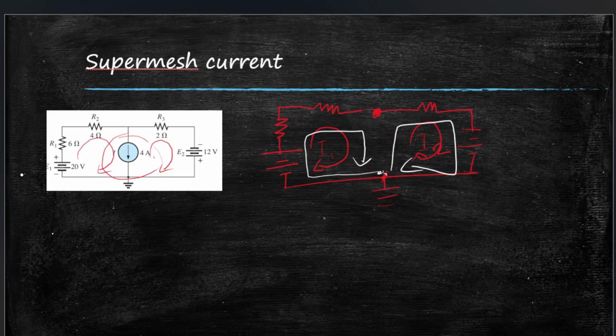So this voltage source is here, E1, 20 volts, and current enters through the negative side, right? So I'll put a positive sign, so 20 volts. And then R1, VR1 will be, wait, the polarities are not assigned. Let's assign the polarities.